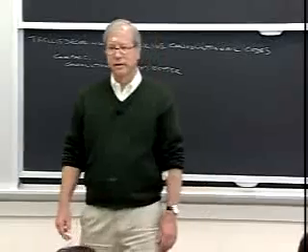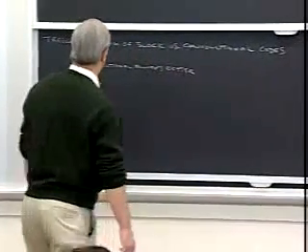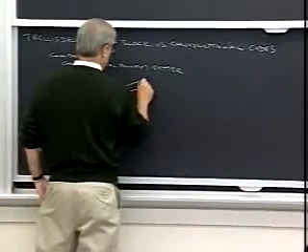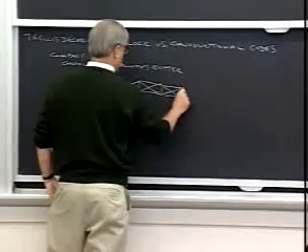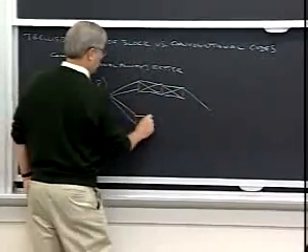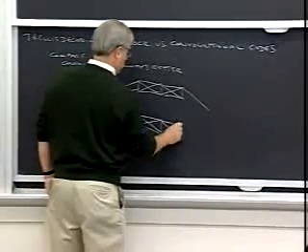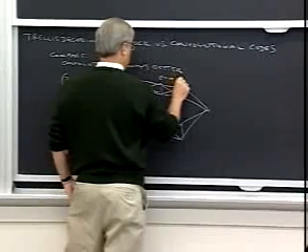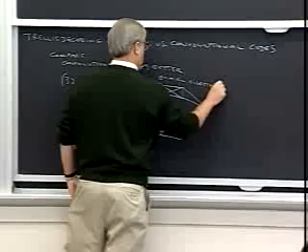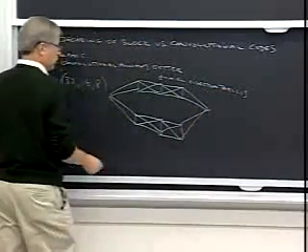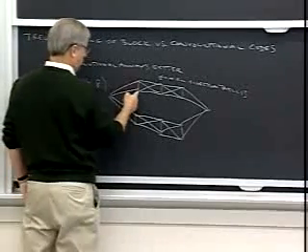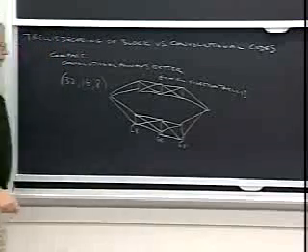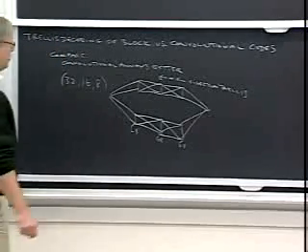Okay, and what's its complexity? All right, if you look at its state complexity, we're looking at the 32-16-8, and all the Reed-Muller codes have 4-section trellises. You proved that this week. If you just measure the state complexity at 4 places, equally spaced with 4 equal sections, then all the trellises wind up looking like this for a general Reed-Muller trellis, 4-section trellis. And for the 32-16-8, it turns out you get kind of 8 parallel sections like that with 8 of these each. In any case, it's 64 states at each of these boundaries. All right. So you could say it's a 64-state trellis.